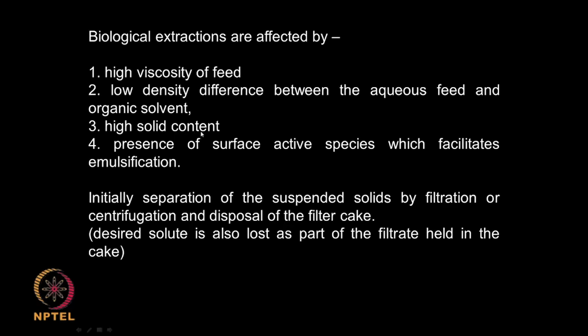The solid content could be very high because we are talking about dead biomass, live cells, broken cells, precipitated solids, salts and media components, and the presence of surface active agents like biosurfactant and other material which may be creating froth.